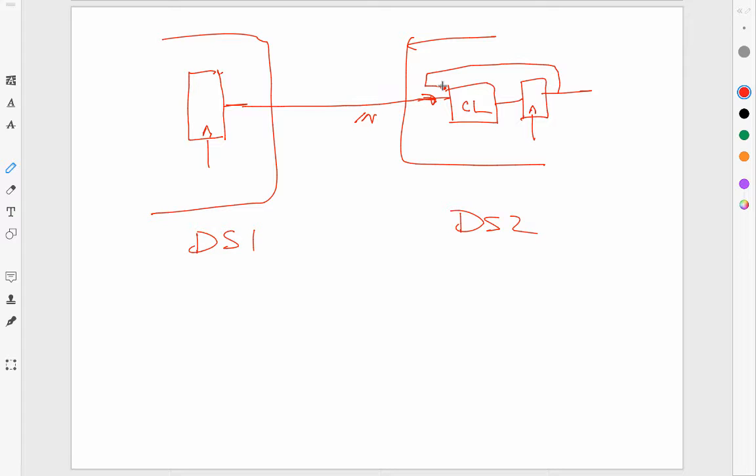Now let's look at what will happen at the clock boundaries. Let's say our system is a positive clock type system. If I monitor this input signal, then it is going to change at clock ticks, generally speaking. What I mean by that is it may not change, but if it changes, it changes on the clock tick. Agreed? Because it's coming from another register. So it might look like the following. If I observe this input signal, this guy, then it might change like this.